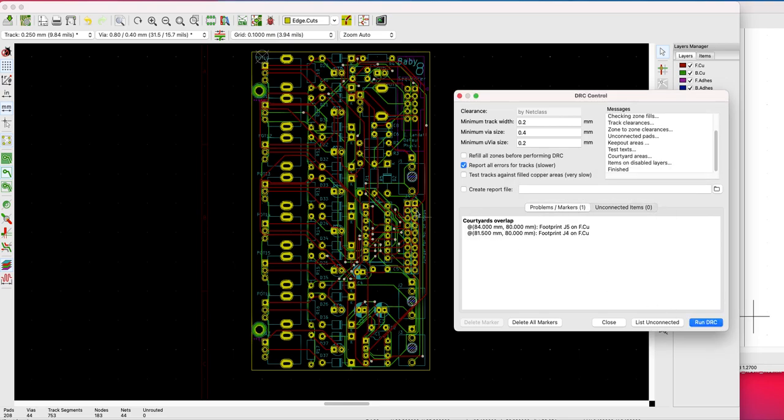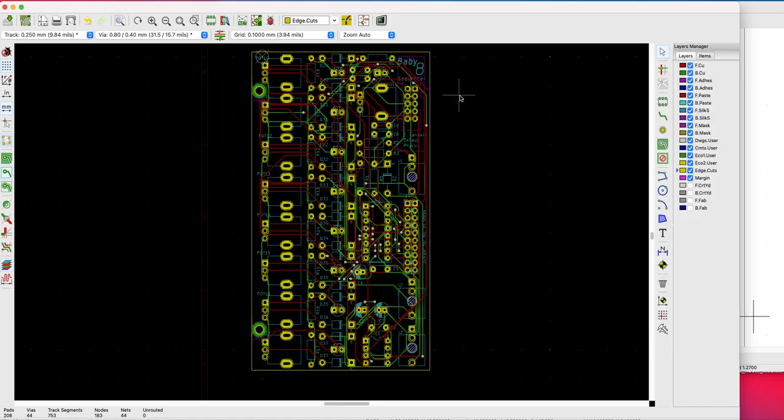The only problem that comes up is the footprints on J4 and J5, which is where we'll be connecting jumper wires. I know I had the footprints overlap because I set them a very specific amount apart, so I'm not concerned about that. I've redrawn my outline, left a little bit extra space on the edges so nothing gets too close. Again, we'll be mounting it with the J1, J2, and J3, 3.5mm mono jacks. Power will be coming in on the back side. The pots we'll be using for the sequencer are cheaper pots. They don't bolt into the case, so I've added some mounting holes.